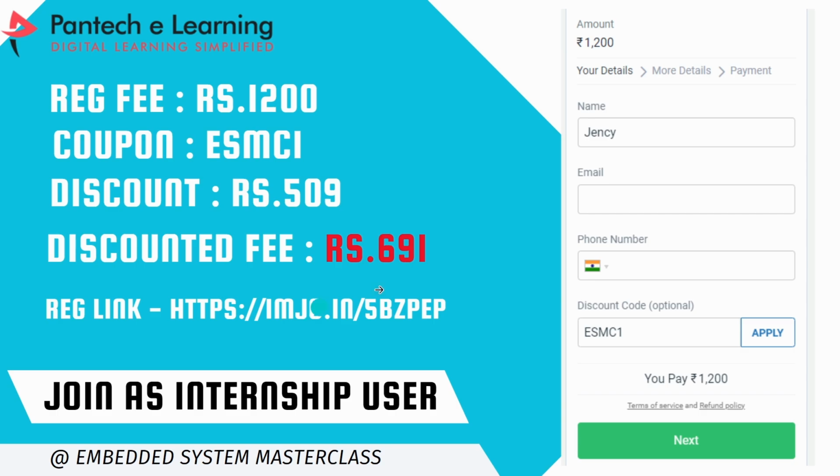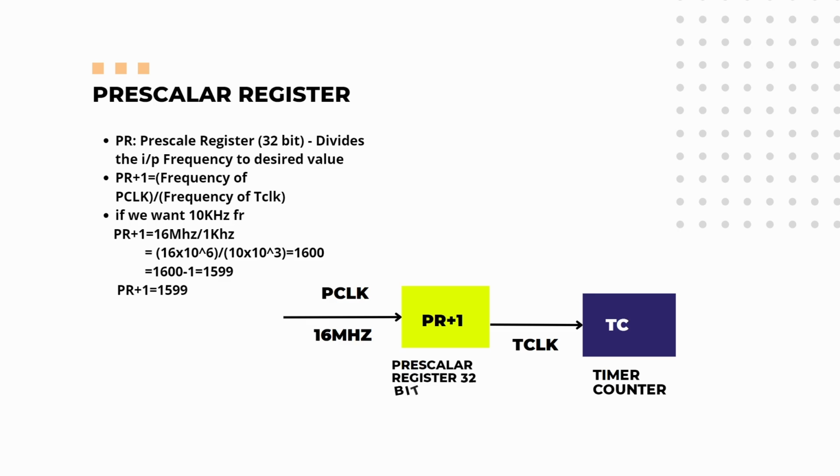Okay, thank you. So guys, next we will get into the topic. Before going to that, we have to set the prescaler for the timer, right? Because PWM is one of the functions in the timer. So PWM is going to use the timer clock frequency only. So we have to give the timer frequency, right? So I'm going to generate the timer frequency. So my timer clock is 16 megahertz.